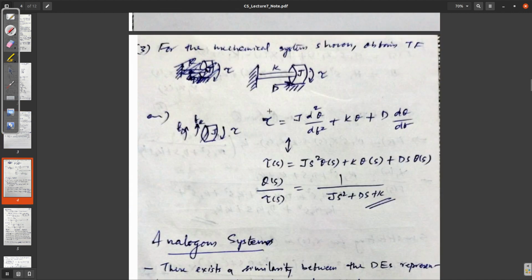Okay. Now let's see a simple example for a rotational system, right? So here this concept for rotational systems is the same, just that instead of thinking in straight lines we have to think of rotational things like torque and angular displacement and angular velocity and so on. So here right away we can write our free body diagram. We have one torque like this, right? Torque like this. We have our two forces opposing it like this, Fd and Fk. So here D is the friction. Okay, here we have a friction and we are modeling that friction as D.